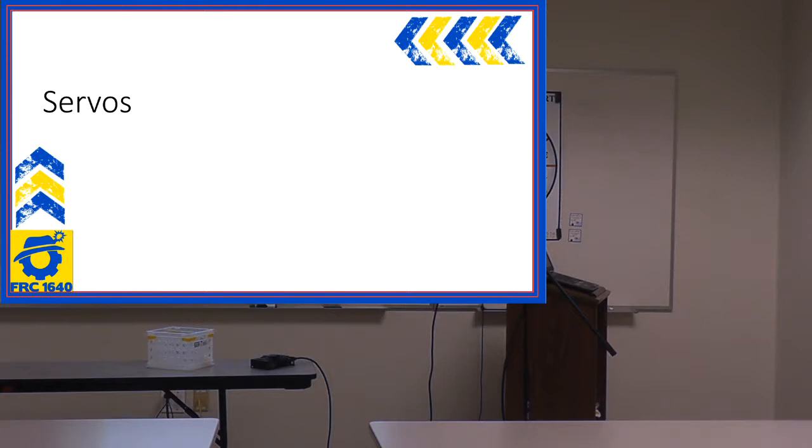There's a sun gear down below. But each set of planets and suns is a stage. Each stage consists of a sun gear, a few planet gears, three or four typically, sometimes 5 planets, and a carrier, and that's a stage.